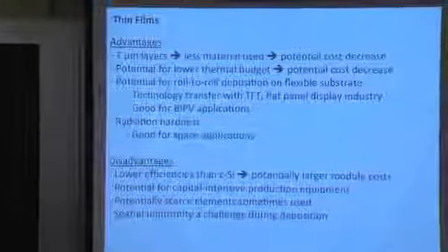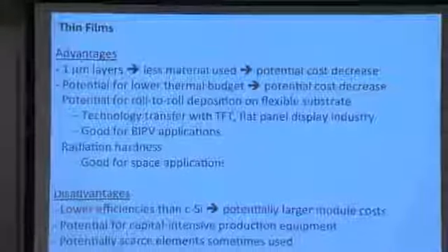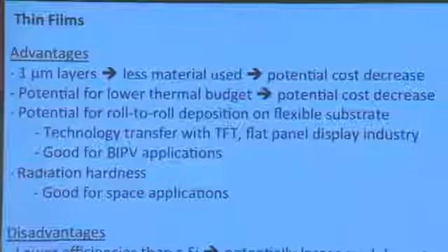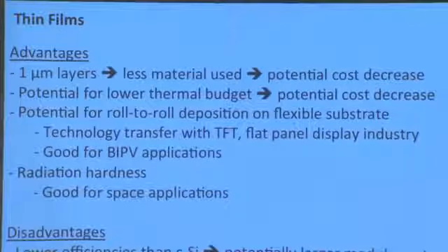The advantages of thin films, quite simply, is that you're using a very thin amount of material. So thin, in fact, that it's virtually insignificant in terms of the total cost structure of your module. One perspective is that if you're depositing a thin film using a fairly low-cost technique, like a closed-space sublimation type process, you may be able to deposit the material for as much cost as it takes the cardboard that separates the modules from each other in the stack that's being loaded onto the 18-wheeler out of the factory. Just to put things in perspective, it's very cheap to deposit these thin layers.